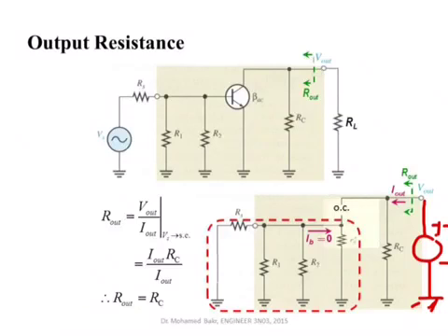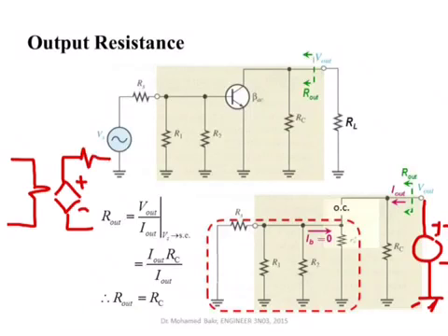And if you remember, we talked about that at the start of this course. We said that the model of an amplifier looks something like this. If you try to put it in an equivalent form, you have an input resistance. So this one here is my input resistance. This one here is a voltage controlled voltage source, so whatever the input voltage is, it is being amplified, and whatever is amplified is being delivered to the output through R out.